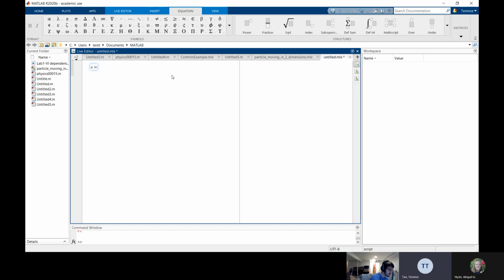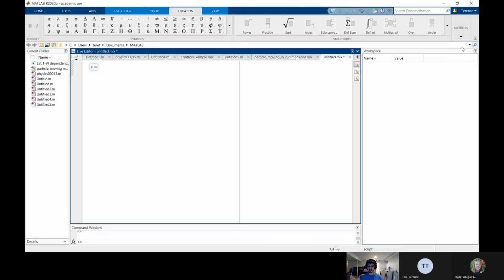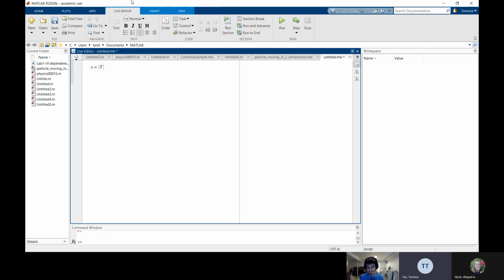So I think X is a vector with two components. Its current temperature and its temperature dot. In this case, I suppose that might be a more accurate way of doing it. But here we're just considering U as something you can pick. You don't have to worry about speeding up the rate at which it's heating or slowing it down. So you only have to consider the temperature. Okay, because those components have to match with the control vector. Yes. In this case, we can fully represent the state of the system using a one-dimensional state vector. There's only one variable we have to keep track of. That is T. If it's 1D, you don't even have to. Yeah. Okay, I guess it looks nice.